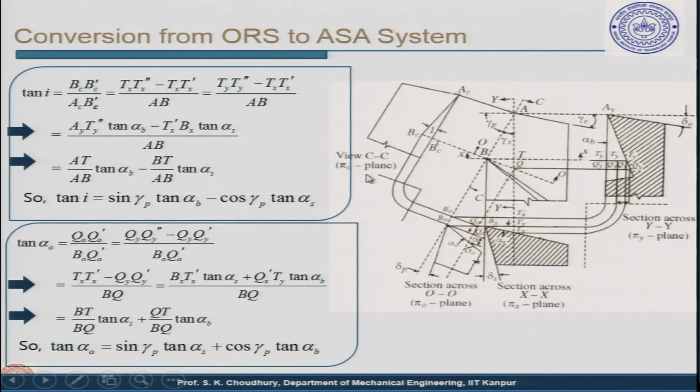Like that we take a perpendicular here, put those points here, then you take a turn and perpendicular to this, project it in here, and then go perpendicular to this surface, go in here, and wherever it intersects it will be on this view.